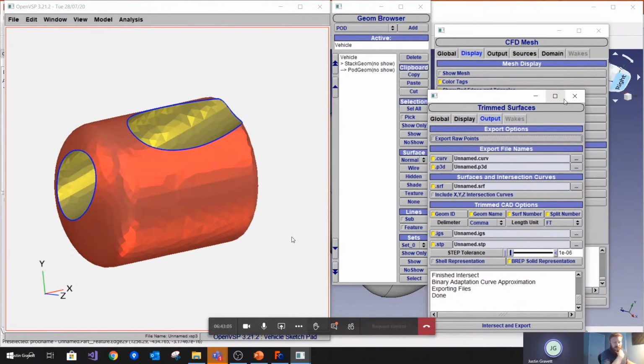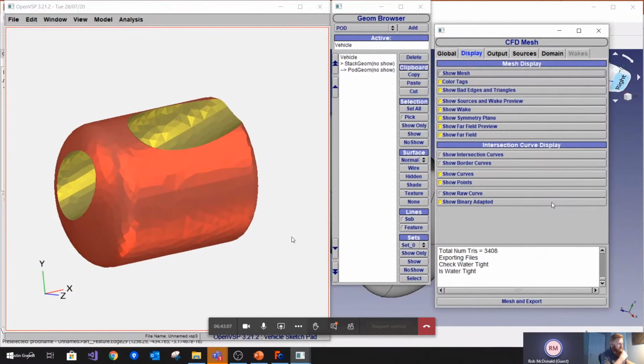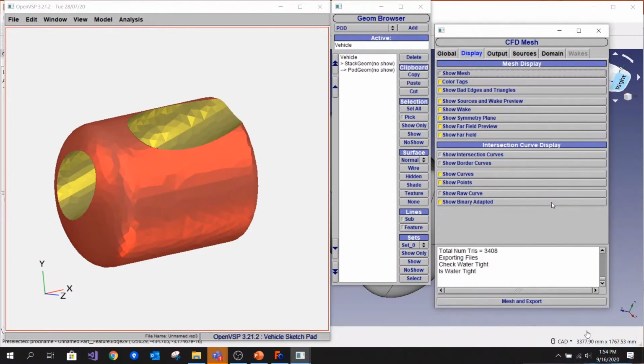We had a question that I'll actually pose to everyone on the YouTube side about what CAD programs are really good at doing fairings between components. I know Brandon has done some, I think in maybe it was NX, but doing a good fairing where you have a variable radius along the intersection, you wrap around the leading edge, but then how do you fair out? How do you blend out after the trailing edge into the body?